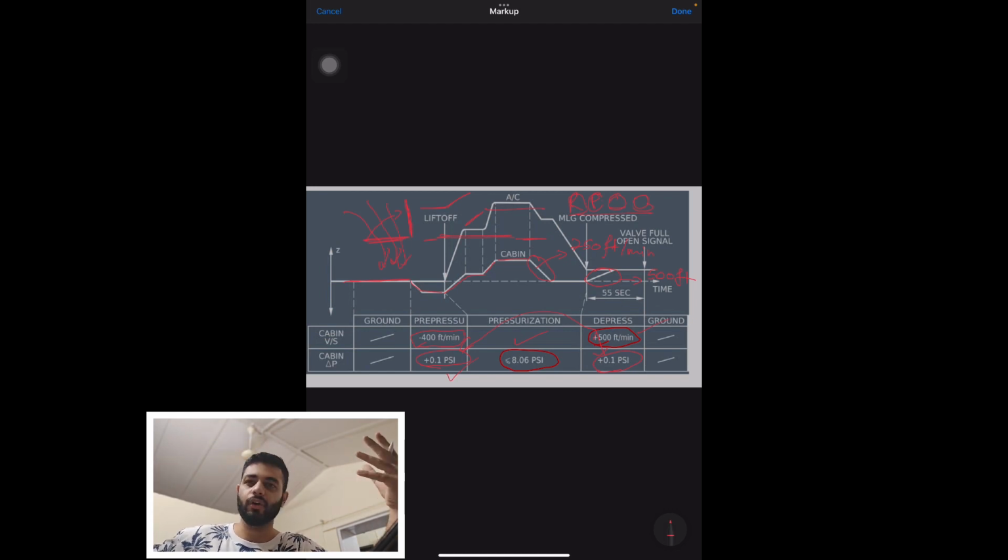In this case, they have called it extract, but it's the outlet valve, are closed. Okay, and your pack flow control valves are closed. Your forward cargo outlet isolation valves are also closed. Okay, so yeah, this is the majority of the stuff you need to know.